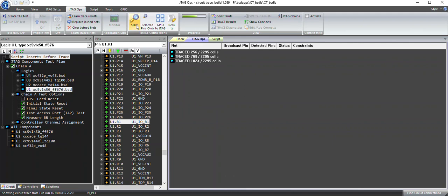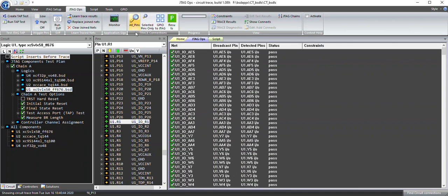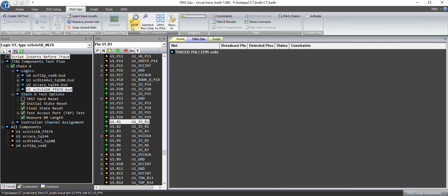And you might have to make a number of adjustments with guards. You can change the guards on these pins depending on the application. So it appears to be repeatable, and at this point, we will insert a fault, which I can do by simply flipping a switch on the board, which will change the connection status, and then we will run all pins again.